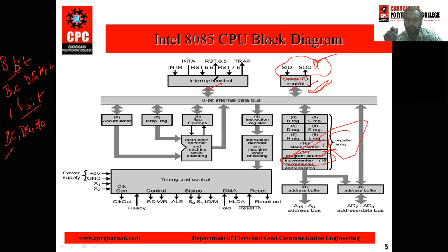When a program is running, if a higher priority program jumps in between, the processor leaves the program at that place and stores the result of the particular instruction, and the address at that time is stored on the stack. It takes the address of the high priority interrupt and runs the higher priority interrupt program.